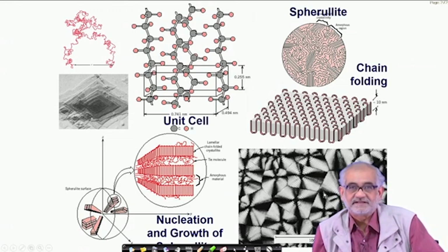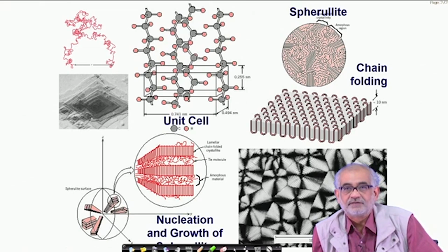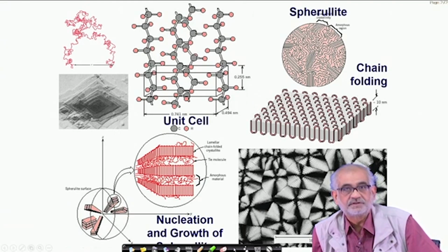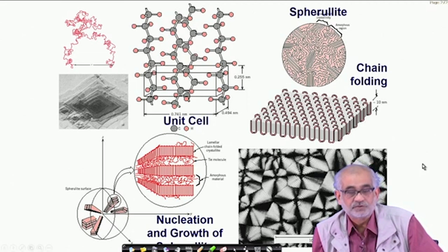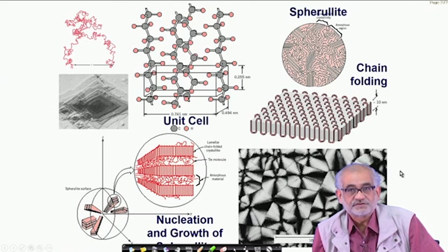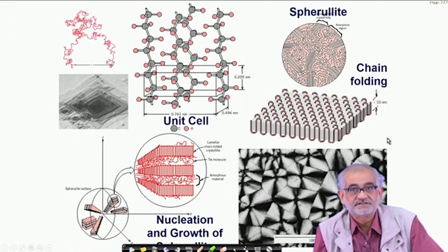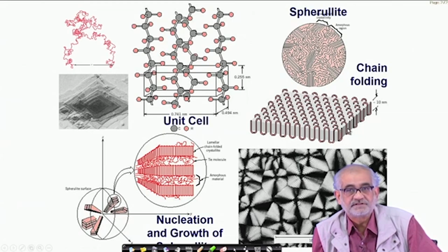So the point I'm trying to say is that while metals could be 99 or more % crystalline with very little amount of crystalline defects, certain types of ceramic materials, particularly the semiconductors or compound ceramics, can also manifest similar 99% crystallinity, or certainly more than 90% crystallinity. Though of course certain classes of ceramics like glasses can be non-crystalline, polymeric materials by and large are non-crystalline with little amount of crystallinity developed because of certain temperature and pressure conditions. And synthetically one can convert polymers into predominantly crystalline aggregates. A large part of it actually is happening because of such a chain folding mechanism.